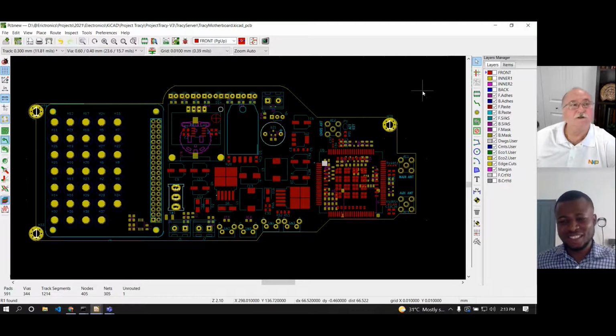I know you may or may not be able to build this board and do an A/B test, but I certainly think it was a great board to use as an example to discuss the process for analyzing a board design and the results. I think if somebody looks at the two different boards layer by layer, and maybe you put that into a PowerPoint, you can see the differences in the way the copper is used. And the final line is the copper is balanced. You're taking very little copper off of the board. It reduces the cost per board and it increases your yield in fabrication.